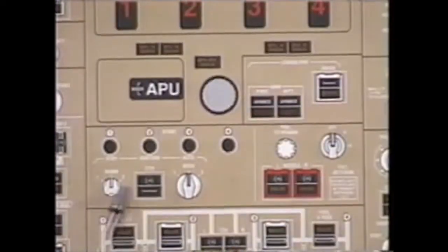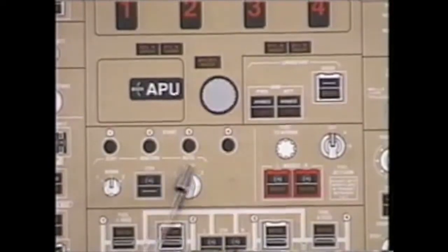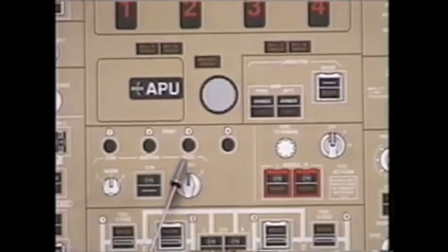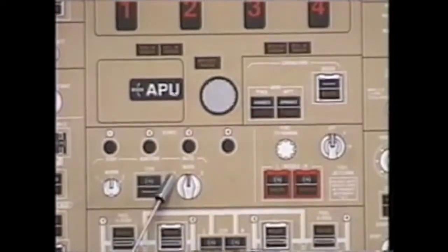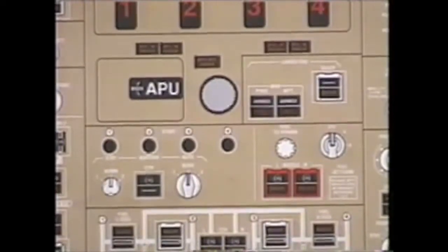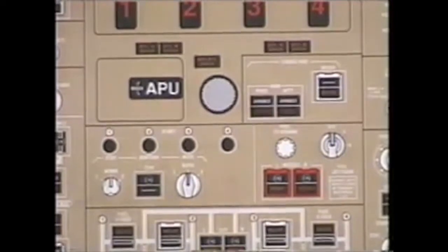Dropping down to our ignition control panel, we have several selector switches here and start switches. Ignition, each engine has 2 igniters. There's a number 1 igniter and a number 2 igniter in each engine. We have the ability to select either or both igniters. Normal operations is to select a single igniter based on odd number flights or even number flights, and selecting both during irregular start procedures. Selecting the appropriate igniter, 4 things will activate that igniter and actually fire it.